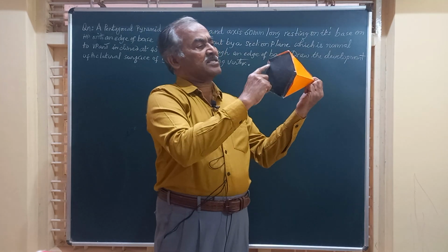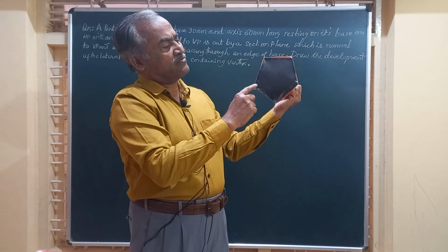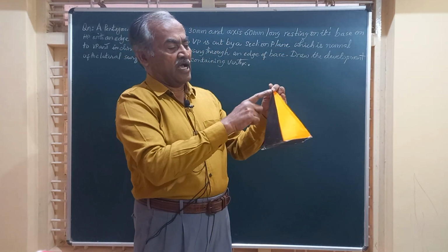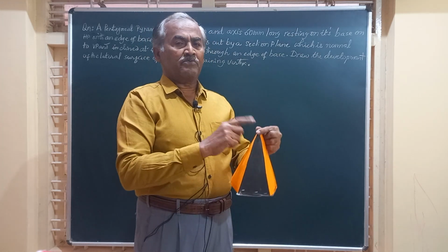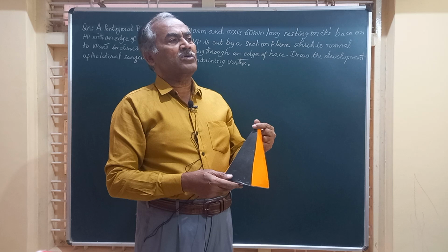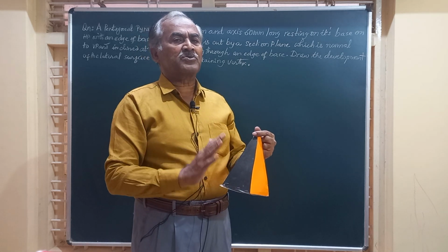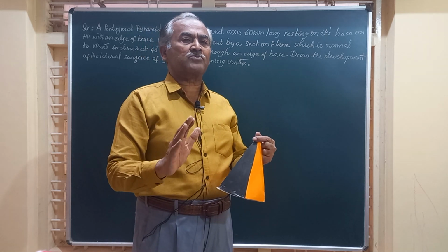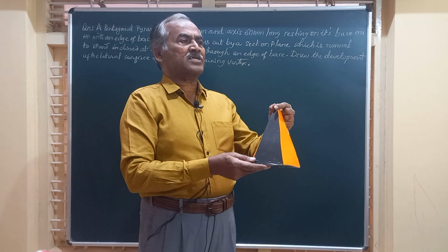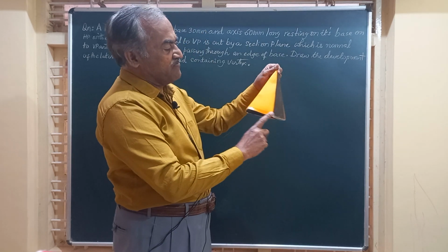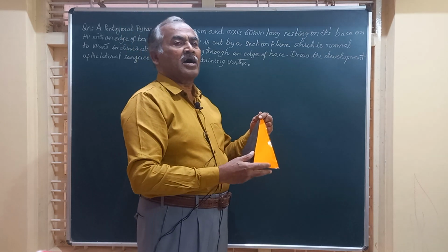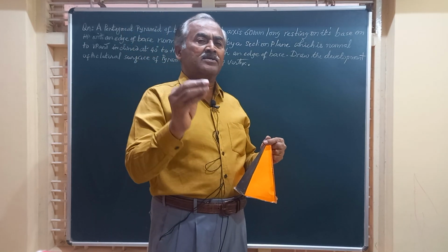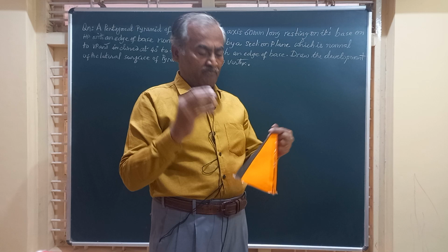Friends, just listen. There are 5 shorter edges for the base and 5 slanted edges for the pentagonal pyramid. Now, first of all, we should see how the object is to be placed on HP. It has to be placed such that one of the shorter edges is normal to VP, and we have to obtain the top and front views of the pyramid.